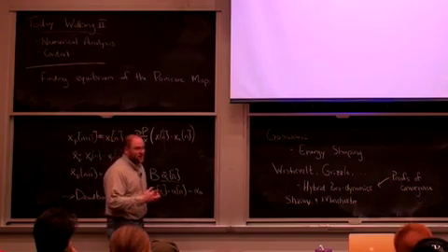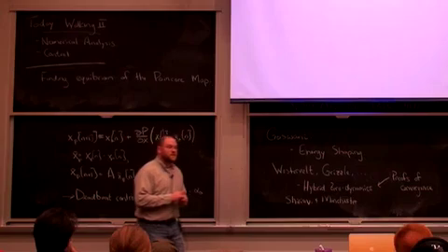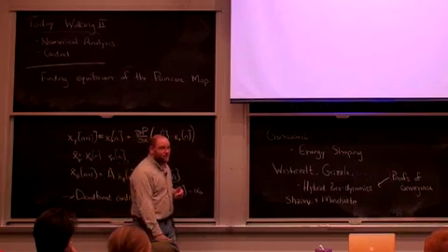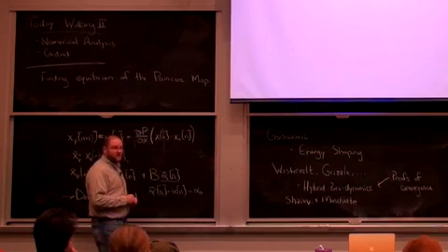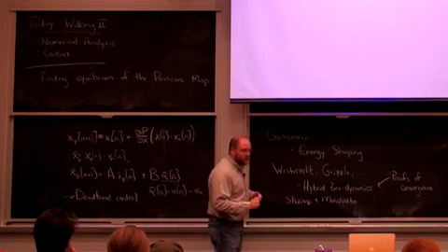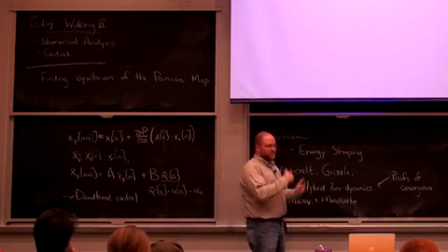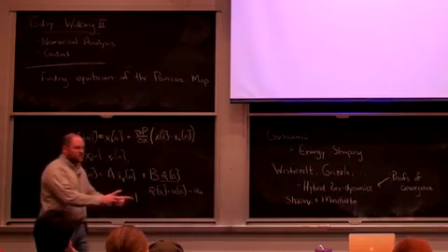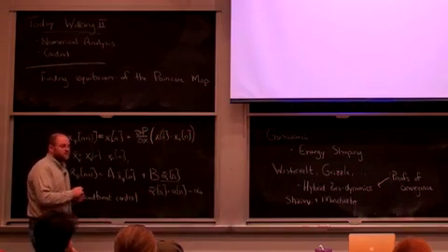And they pretend they're a fully actuated system and do trajectory tracking. Yeah? And when they're doing their trajectory tracking, they have to make darn sure that foot doesn't roll off the ground. Right? But if you watch the videos of Asimo, you're going to see it's always got one foot flat on the ground. Running is a small excursion. They just give up on stability for a little bit until they go back to the place where they can catch on the ground. Okay?